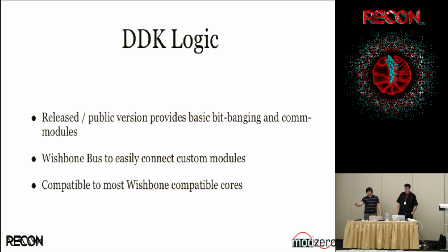And just to go one step further, the reason you need a bus, or the reason we've done the heavy lifting for you, is that now it's very easy for you to have 8 modules running simultaneously, which would not be possible if you were doing an FPGA design otherwise. You would have to start writing a bus architecture. So we did the heavy lifting for you. Now you just go out and grab modules from OpenCores, write your own modules, and integrate them.